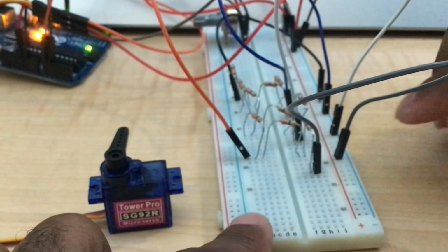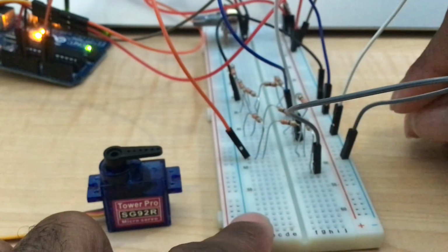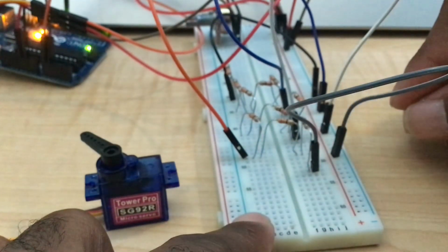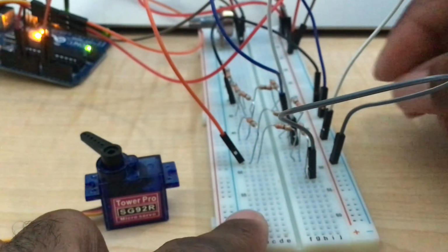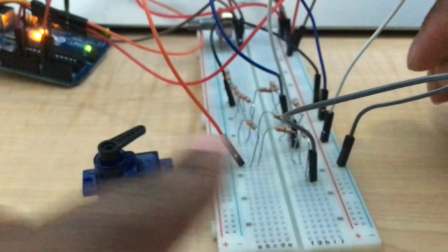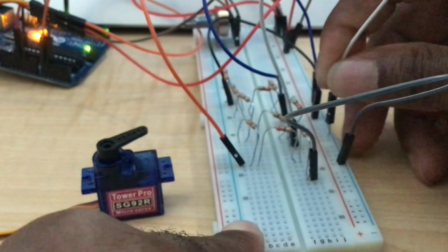Now the servo is controlled from the output of the DAC. We see 5 different positions from the servo. This is different from the potentiometer because with the potentiometer, we see a continuous or analog position output. The DAC provides a stepped or discrete position output.